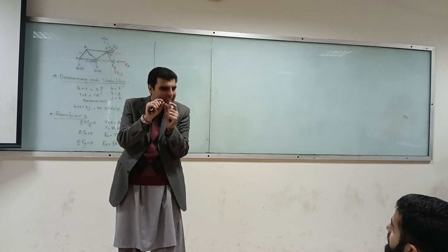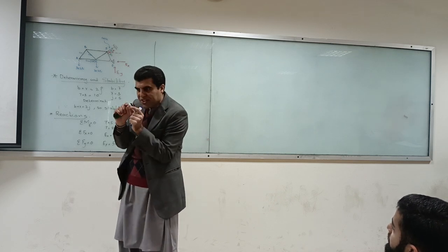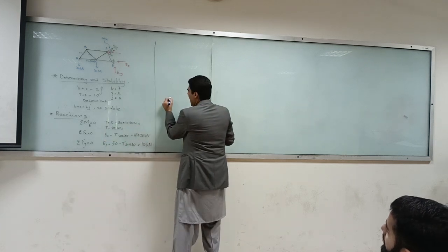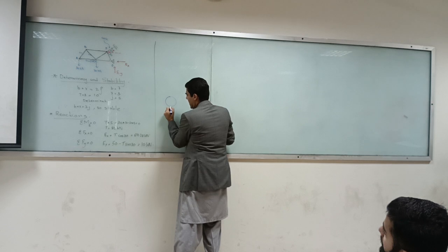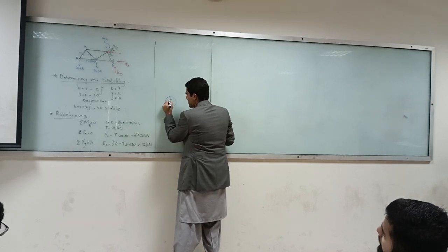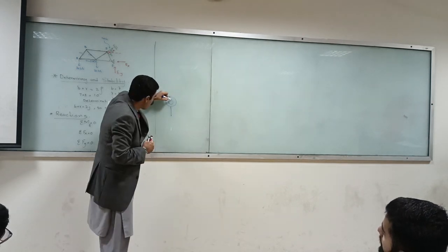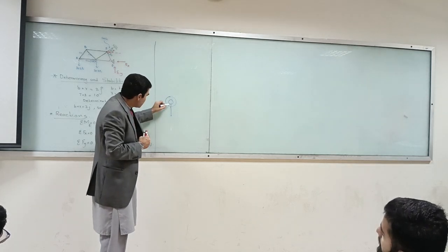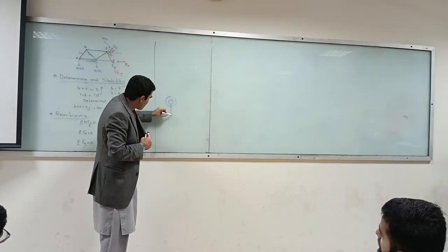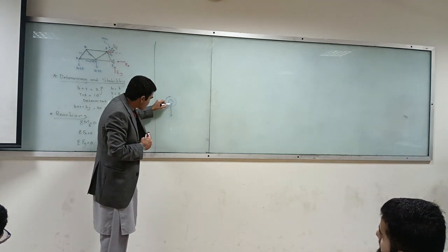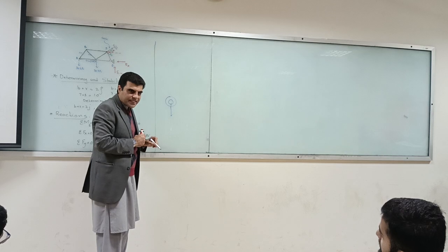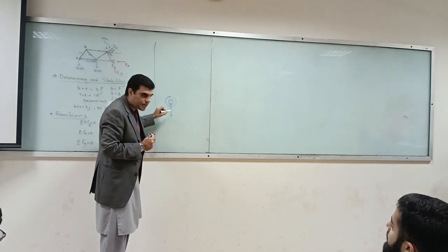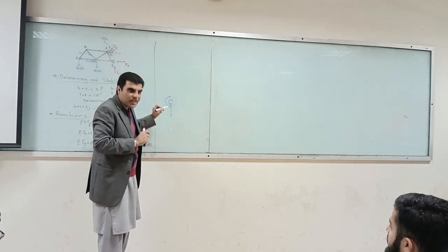very small eccentricity, very minute. If I have a load over here, imagine this is my pin, and I've got load hanging like this. Now if it is hanging perfectly in the center, then I agree, there is no lever. But if it is slightly off center, then there can be a very small lever.